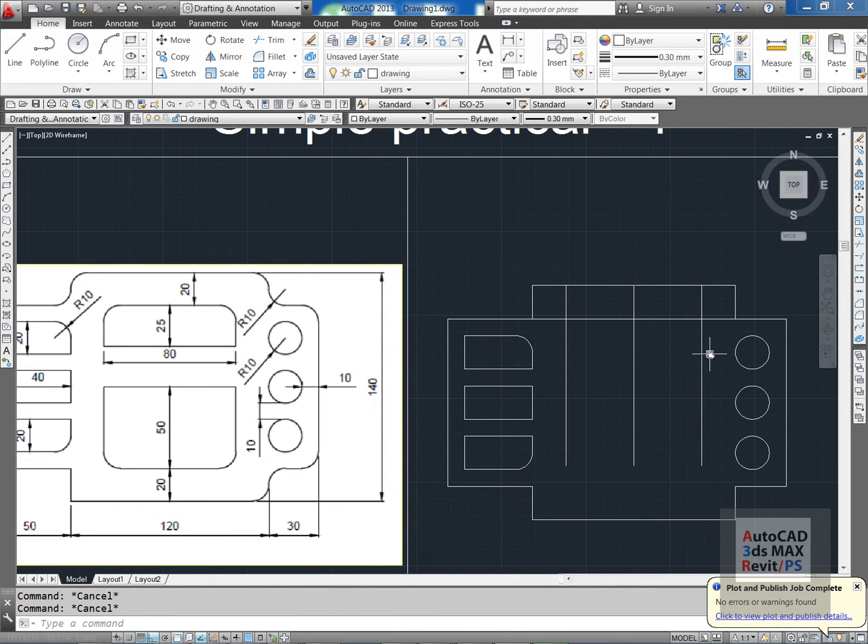So, I will make a distance of 20 down, and the rest of the line I will trim it. So, TR, selection, enter, you do not want this, and TR, selection, enter. You don't want this and you don't want this. No need of making of this now, and this is 25. So, offset of 25. So, this is that point, trim. Now, I will not remove these lines because this is going to help me to make these lines.